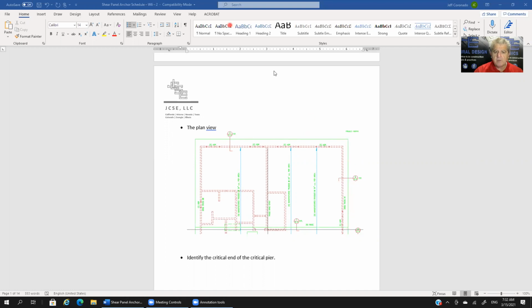It looks like we have repetitive framing. Specifically, it looks like these are trusses, but we have repetitive framing that goes in this direction. I believe here north is up, and I'll just show that over here. So we'll call that north. So the framing is going north-south in this roof. Let me clear the screen. What else do we have? In particular, we're going to look at what we would call the shear wall line across the north perimeter of the residence. So that's our shear wall line.